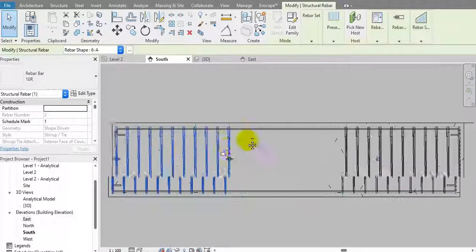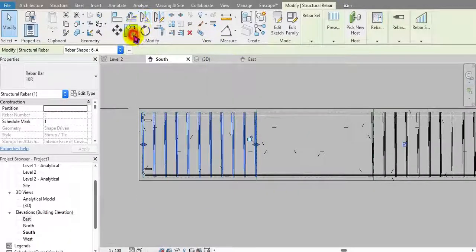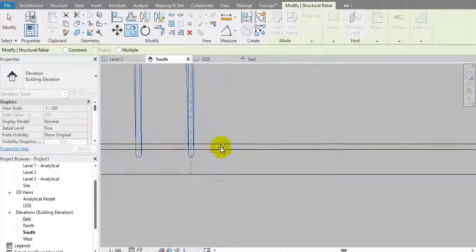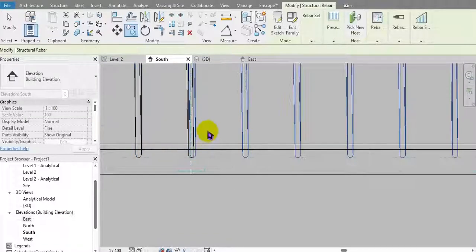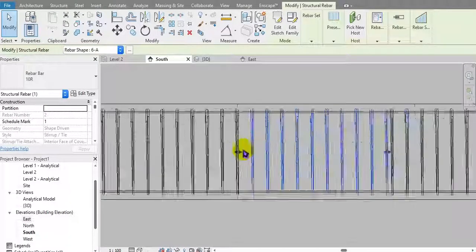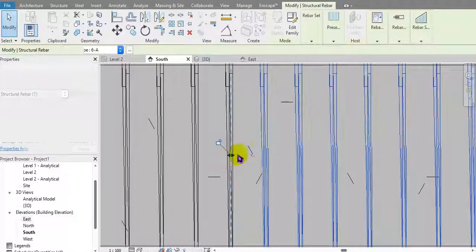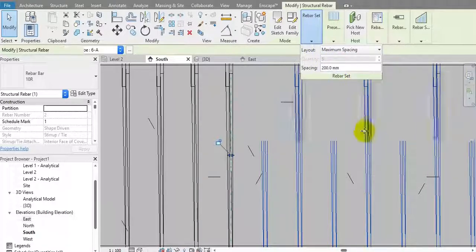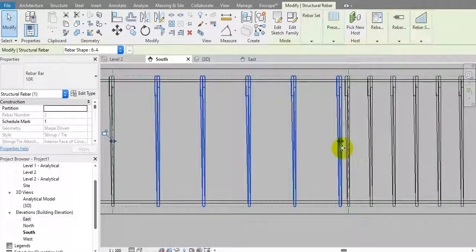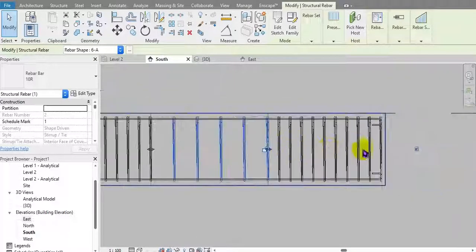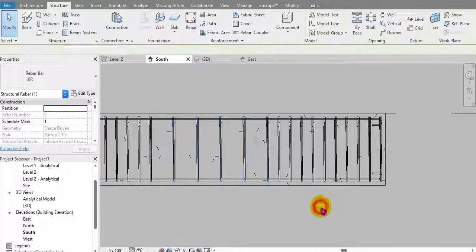Okay, so for that you can copy the same thing using the first point, and you can have the second point right here. Okay, click on overlap, and now you'd like to turn off this, so the first bar has been turned off. Now you can adjust this spacing right into 200. Okay, alright, and drag it up to here, and I'd like to turn off the end bar.